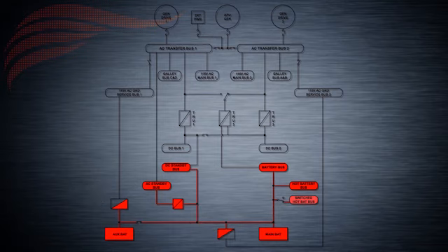During alternate operation, the power sources for standby power are the main and auxiliary batteries. If engine-driven or APU power were lost, both batteries would power the system's standby loads. In alternate operation, the AC standby bus is powered by the static inverters, which convert DC energy from the battery charger and battery bus. Both batteries power the DC standby bus, battery bus, and hot battery bus.